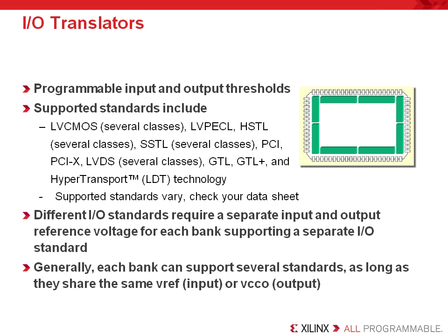This is an important requirement for users to anticipate because it does limit the I/O standards that can be used for the other I/O pins in the same bank. Notice in the diagram above there are 8 different banks shown. That is basically how the chip is broken down along the edges of the die. So within these 8 different banks, you can have many different I/O standards.